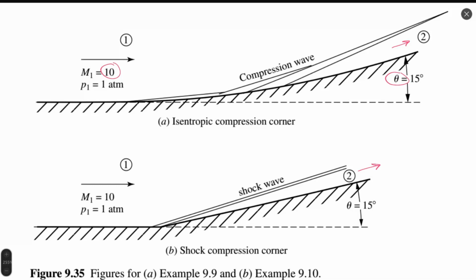So for us, I will find first the Prandtl-Meyer function, nu of M1, according to the formula previously shown for the Prandtl-Meyer function, or I will use appendix C from Anderson. Okay, I see that the Prandtl-Meyer function is equal, let me check, 102 degrees.